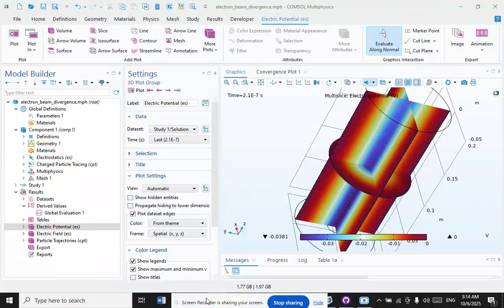The cost reductions offered by EB welding are particularly attractive during the fabrication of safety-critical primary circuit components for nuclear power generation, where the adoption of higher energy density fabrication technologies offers a step change in plant construction economics.